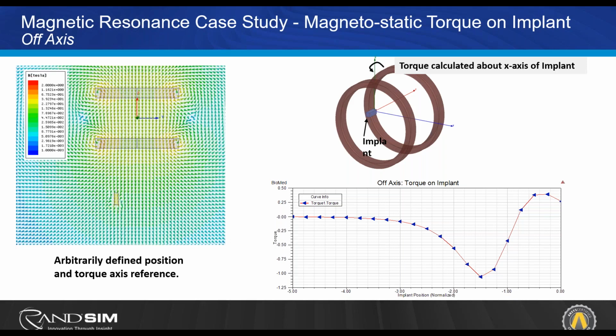And not only that, just as I said before, with the testing suites, for high frequency devices, for transmitters, you can take these models now and incorporate them into that testing to get that level of analysis. So when you're doing your physical testing, you're going to be able to do so with confidence, because once you're getting into that chamber for radiated emissions, for susceptibility, for conductive emissions, those failed tests require changes, require time, require additional testing, which is more money. And this cycle without simulation repeats itself until you pass. So getting the idea of how your device is going to function within the simulation environment first is confidence building, and this allows you to make informed decisions on your redesigns.